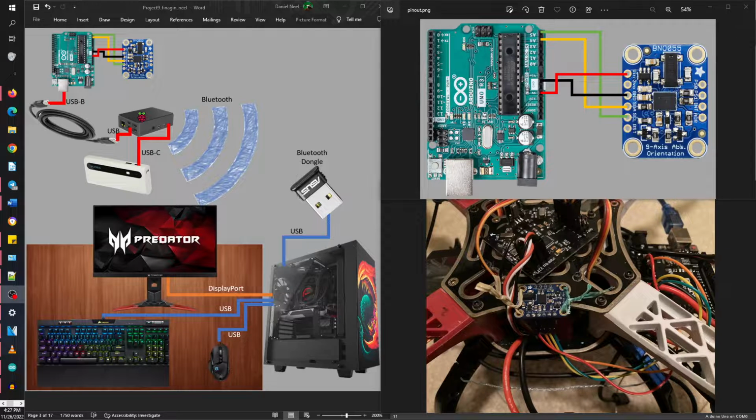I'm Daniel, and Brad will be our pilot as we show off our quadcopter-mounted IMU module capturing roll, pitch, and yaw, transmitting values over I2C to an Arduino Uno, which formats and reports the results in degrees to a Raspberry Pi over USB, and ultimately transfers the IMU data to my host machine via Bluetooth.